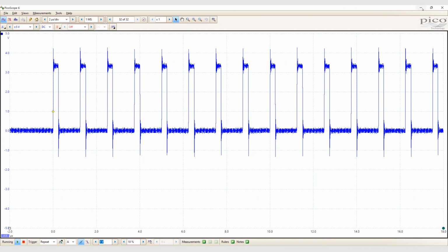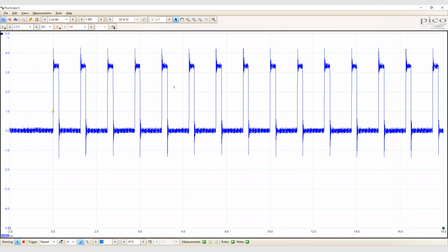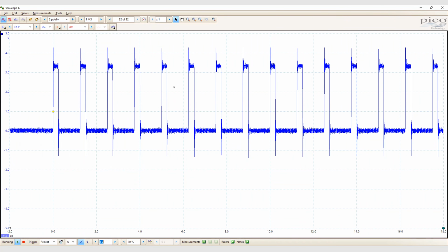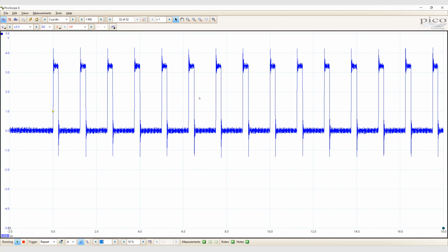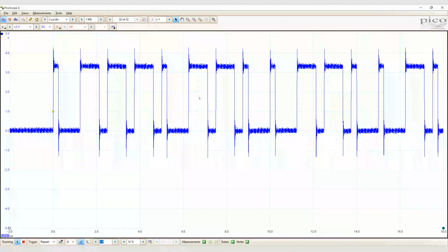So that's one way, and then another way to generate these pulses is through the PIO, and that's a major one. It's almost like a separate CPU on the Pico, and it actually is quite a differentiator compared to other processors. It's an additional processor that's just made for turning bits on and off and moving data around. And that's what we're going to use for this class.